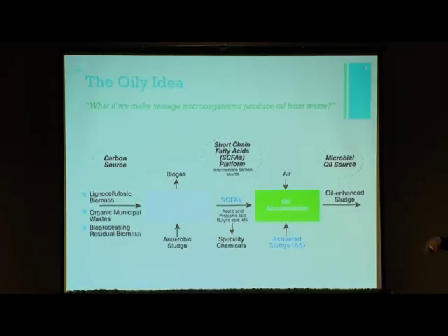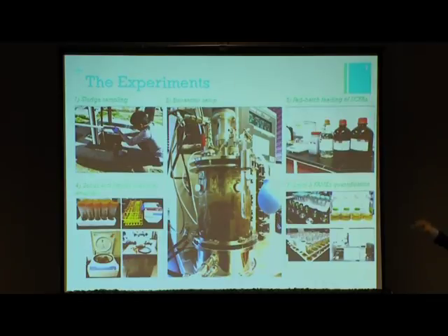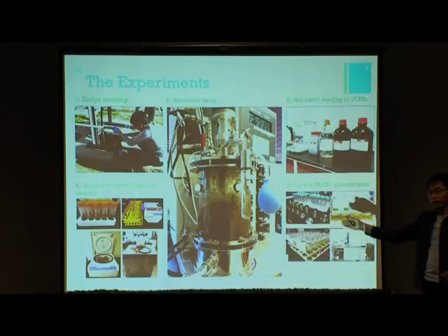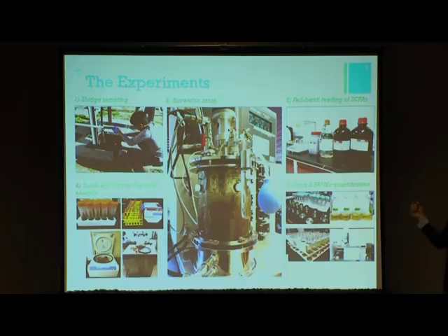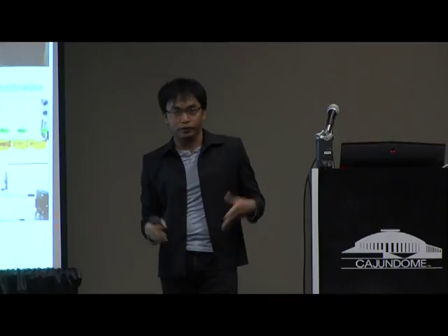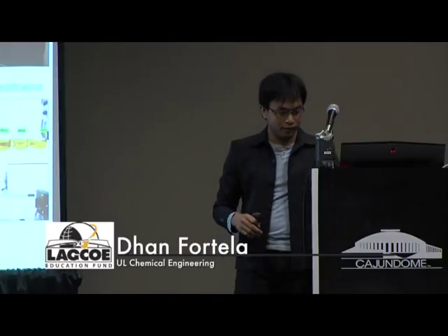And so, basing on this idea, we set up different experiments, but this is the common procedure for all the experiments we did. Hundreds of treatments, this is a common method. Sampling of the activated sludge from a wastewater treatment plant, that was me. The bioreactor setup is a 5-liter bioreactor in the chemical engineering lab, feeding them with the different acids: acetic, propionic, and butyric acid, and after that, sampling and analysis, then further analysis. So that's the whole story that I did for 3 to 4 years.